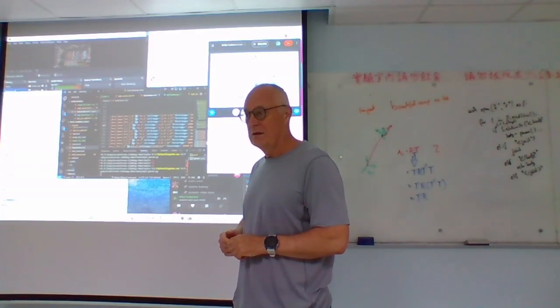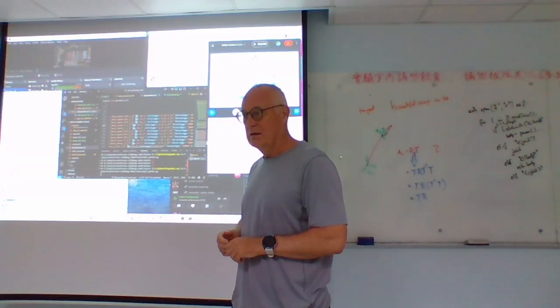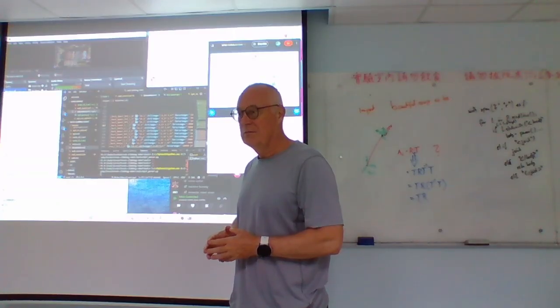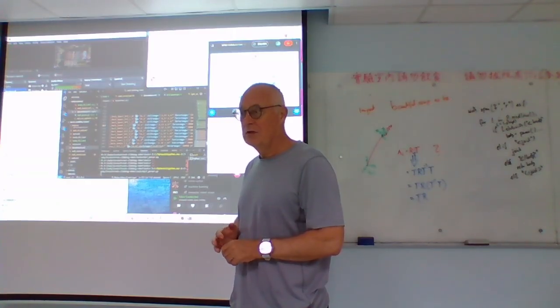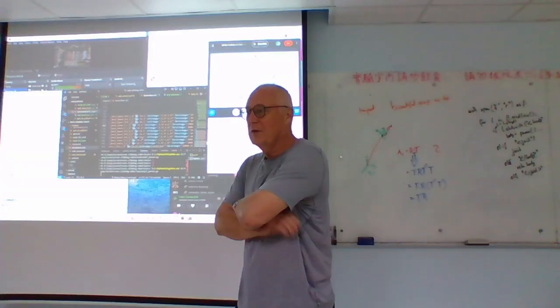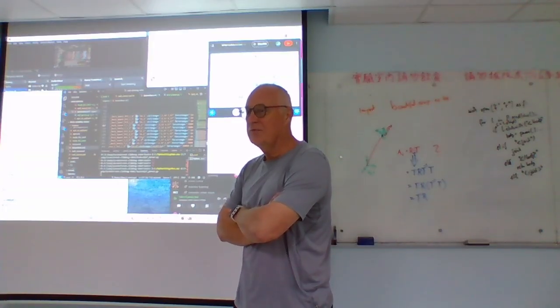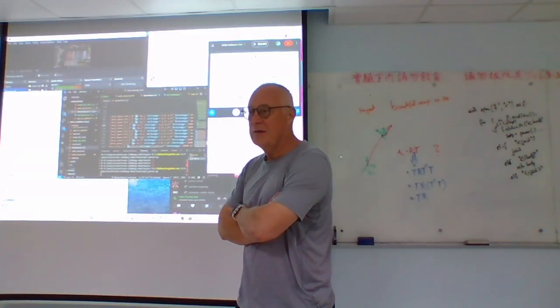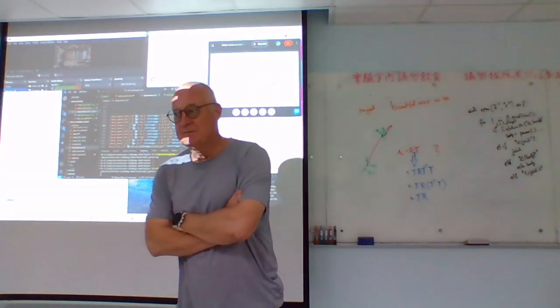Oh, okay, I just know that. But we never define KP in simulation like Gazebo, Isaac Sim or ROS. Usually you do. Usually we don't do it. Yes, you do it all the time. You have to do it, unless you use the default values that it gives you. But you definitely have to tell it whether something has a motor attached to it or not. Every simulation, Gazebo, Isaac Lab, all of them work the same.